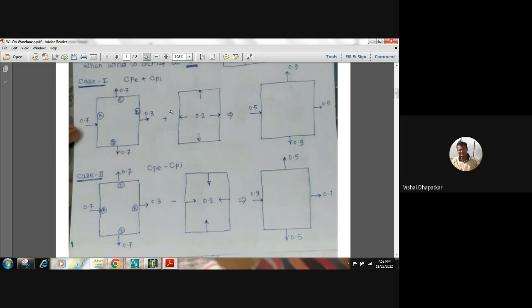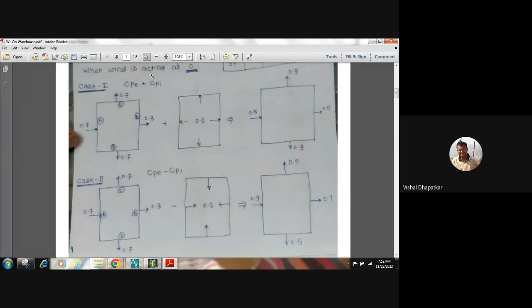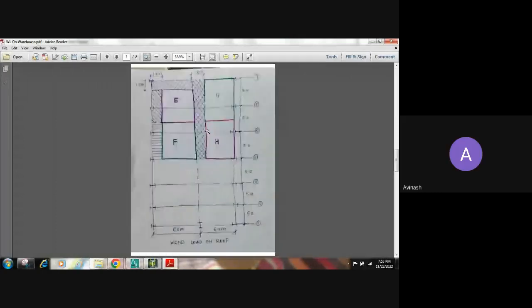यस सर. तो ये आपका फ्लैट सरफेस के लिए होगा और रूफ के लिए भी होगा. और ये इंटरनल प्रेशर कब आएगा? जब आपका स्ट्रक्चर क्लोज रहेगा तब भी आएगा. अगर आपका स्ट्रक्चर ओपन है तो ये केसेस नहीं आएगा. बराबर. सिर्फ आपका एक्सटर्नल प्रेशर कोएफिशिएंट आएगा, इंटरनल 0 रहेगा अगर स्ट्रक्चर ओपन है तो.